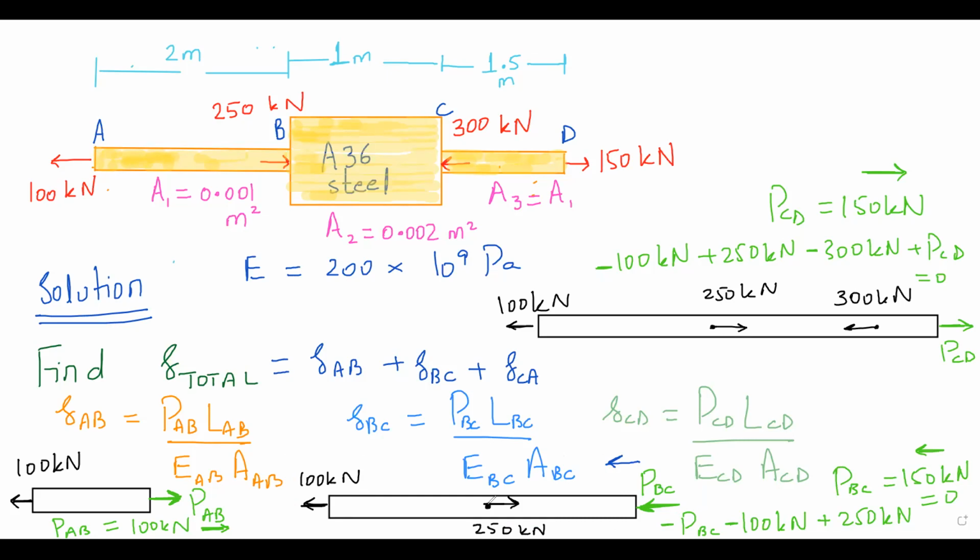And if you sum both of them, 250 minus 100, this chunk is like this. So this rod is in compression. So my BC looks to me in compression. Right? Look, 250 minus 100, so you have a resultant in this direction. And in order for statics, you can see PBC I came up with towards left. So this bar looks to me in compression.